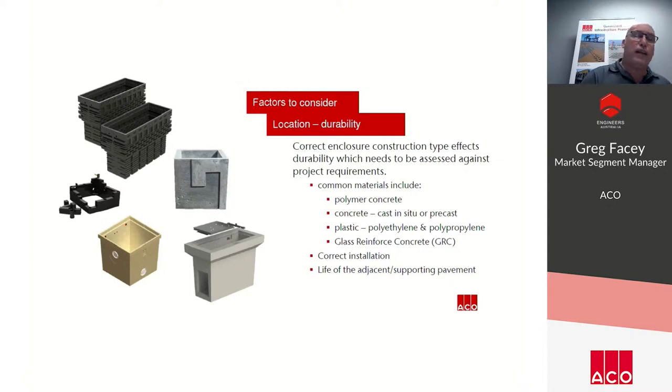So we've seen plastic enclosures diversify over the years from the traditional single wall pit, and we'll discuss that later in the presentation, which would be more a single wall plastic pit for a lighter duty application. Now in the industry we see a twin wall plastic pit, which will take a much higher load, often up to a Class D. And also another material that we see in the industry is glass reinforced concrete, or GRC.